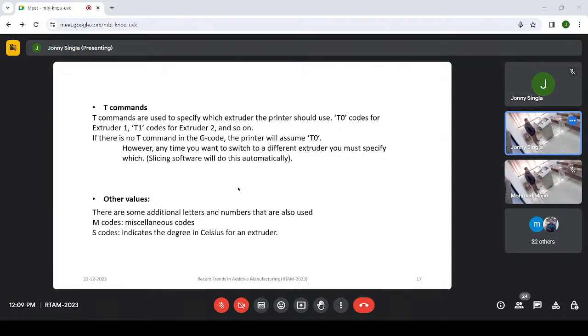If an extruder is being changed inside the software, we change the tool by putting the word T1 or T2 or T3, whichever tool we want to use. Sometimes the opening of the extruder is constant. Sometimes we want more material, but it's not always that we have to pressurize the flow, because it can cause some defects. So we can use an extruder with a bigger diameter.